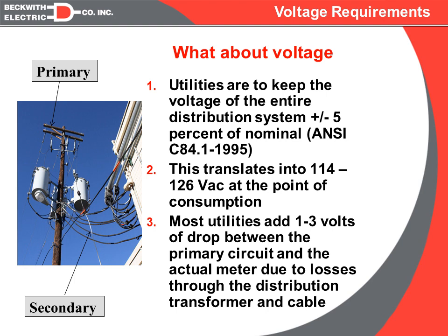So the only voltage drops we're concerned about are the voltage drops getting it to this point and then getting it through the distribution transformers and to the meter. Once it hits the meter, any additional voltage drops within the customer facility are the responsibility of the customer.